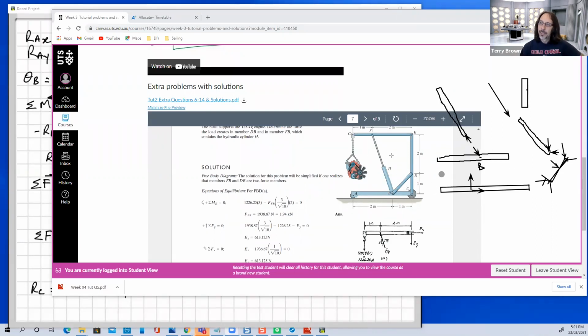The other way is, if you did a computer model of this and used finite element analysis to solve it, you could do it that way, and that's essentially using the computer to do what I was just talking about, looking at the deflections of the members and the relative stiffnesses of things to work out how the load is shared amongst these over-constrained reaction forces. Interesting. Thank you.